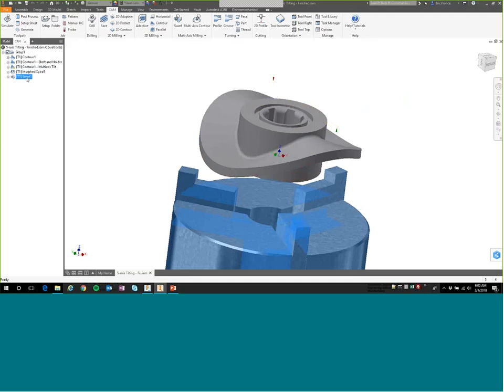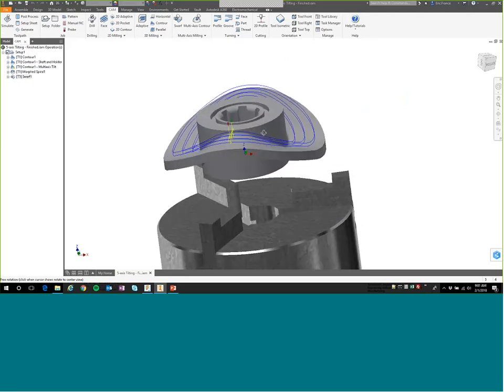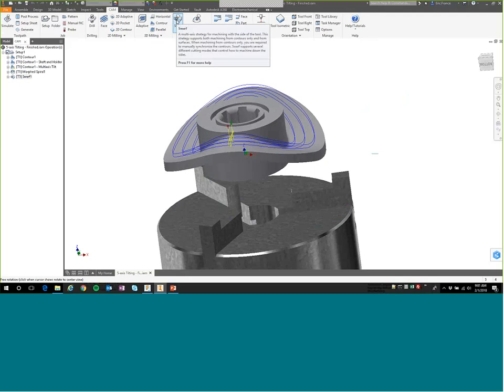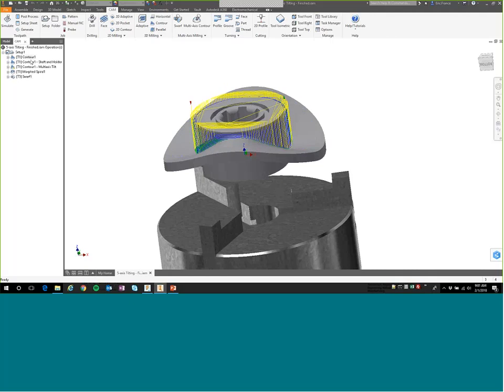So as an alternate to that, if we look at the swarf option, swarf is going to move the part so that it is in line. You can see that preview right up here. We're moving the part so that it's in position so we can use the long edge of the tool along that. In this case, we're doing 3 depths, 2 passes to get to that finished geometry without running into the situation where we're overloading the tool too much.